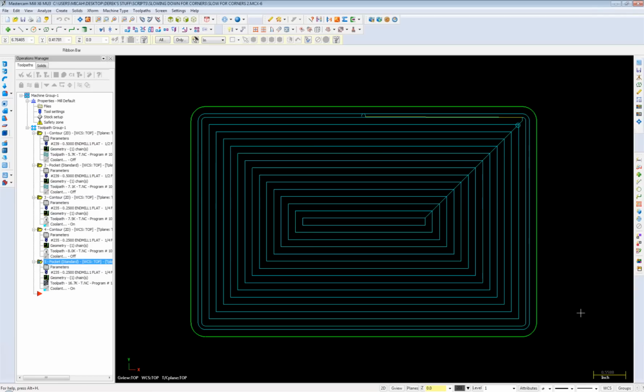Yeah, it's kind of like an accuracy setting along with the high speed, so some of those things can be turned on and off when activated. So it's not on by default all the time. As long as it sees the code, it defines the accuracy at the same time as it activates. One thing that can happen is there are some machines that have it on by default, like the Haas. It's set to medium by default, like in the newer ones.